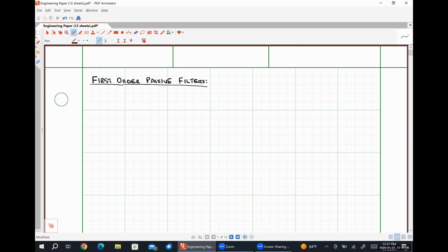All right. So let's start with, I hope, a fairly simple and straightforward question. What is the purpose of a filter? In general, what does a filter do? Stop certain things from trying to get through. Absolutely right. Like the filter in your car, you have multiple filters. You have an oil filter that's stopping particulate matter from mixing in with the oil and causing buildup in your engine. You have a cabin air filter that's just trying to keep debris out of your cabin air. So generally speaking, a filter is something that lets some wanted portion of something pass through, and rejects other things. So in circuits, a filter is something that passes certain frequencies of signals and rejects other frequencies of signals, okay?